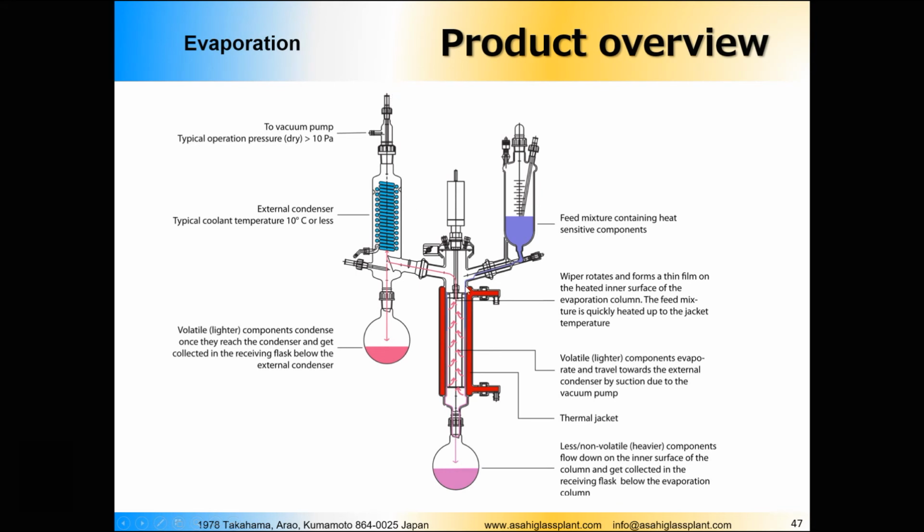The problem for the rotary thin film evaporators and for the short path evaporators, the main problem for them, is that not many people really understand when and why they need this kind of equipment. As I told you already, it is relatively expensive compared to the rotary evaporator. If you compare similar performance, the thin film evaporator would be maybe 3 times more expensive than the rotary evaporator. So when do we need the thin film evaporator? Let me explain it to you